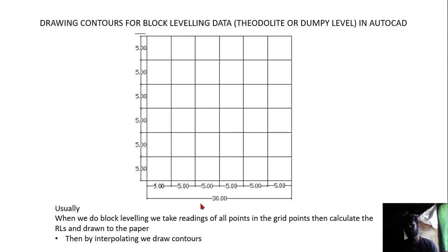This usually happens in the sixth semester of the course. Okay, if you are doing it with a theodolite or dumpy level, and you find difficulty with the manual interpolation and then drawing it, then to make it simpler, contouring or drawing the entire contours using SWDTM and AutoCAD software, you just need to convert the manually taken points or calculated RLs into the predefined format for SWDTM.